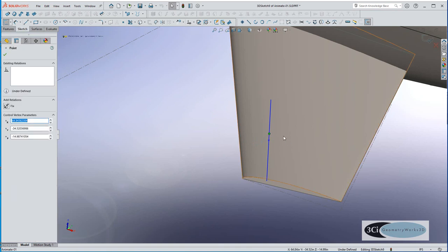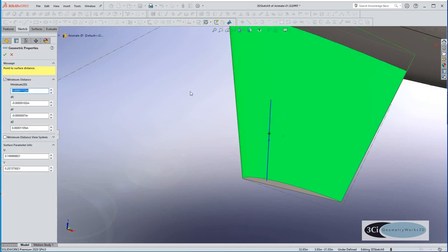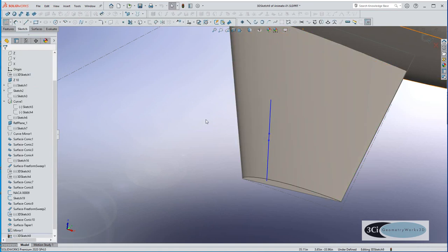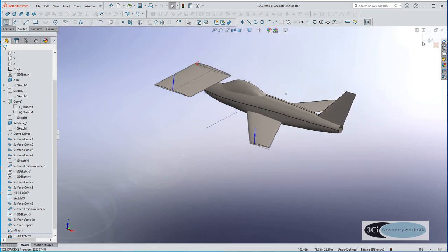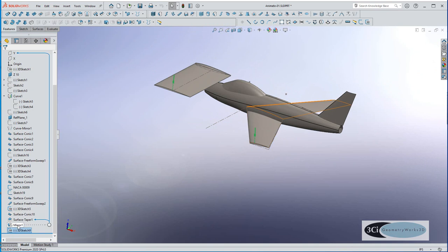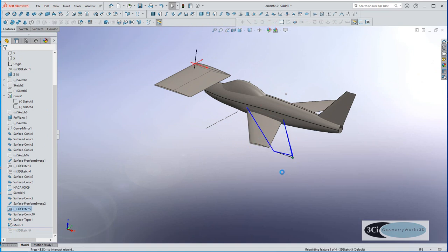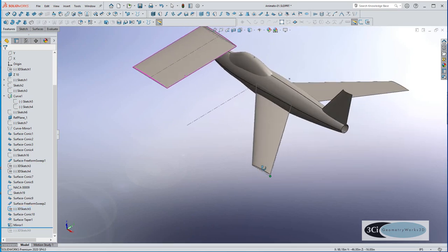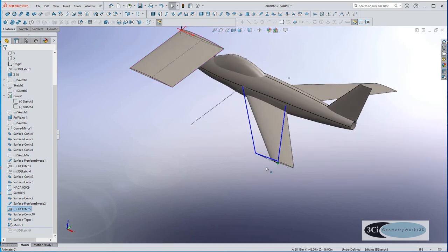We paste in the measured distance up that vector. So we've created a vector, we've offset a point, and then we measure that point to the surface, and we find that it's quite close, or essentially on that surface. So this is the simple method that we use to create a transformation surface by using a simple reference surface, and then two systems, in this case lofted surfaces, that map the original simple surface onto a more complicated destination surface.